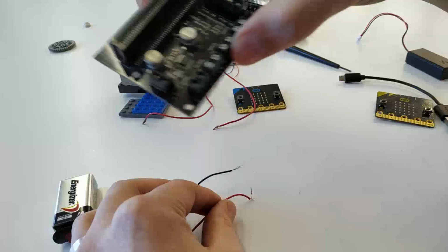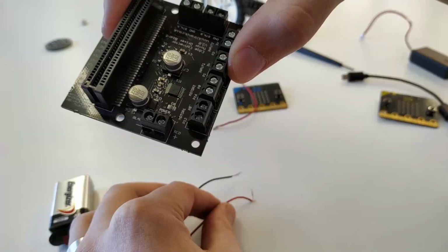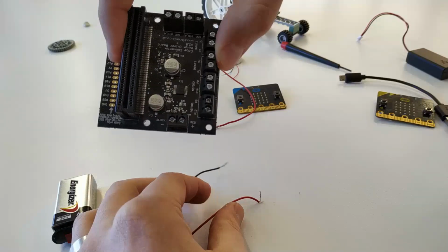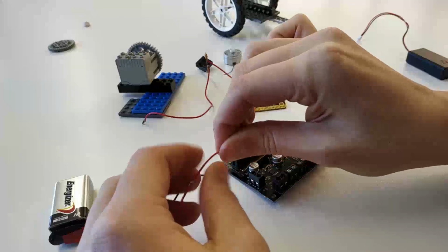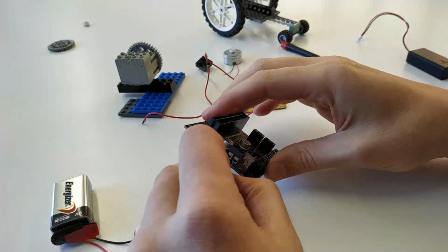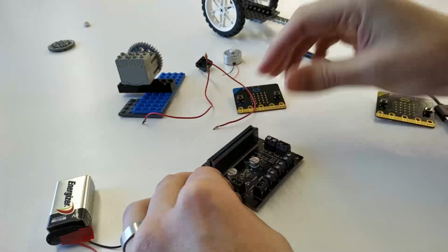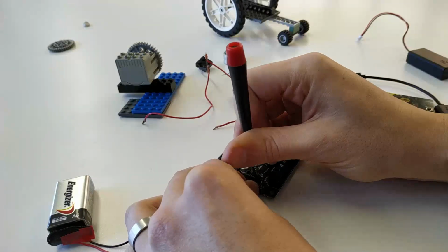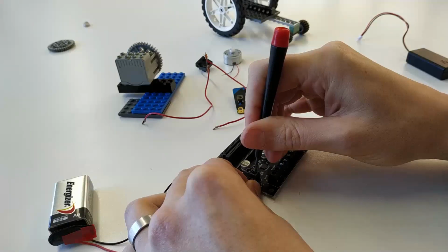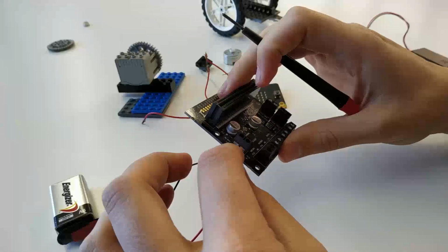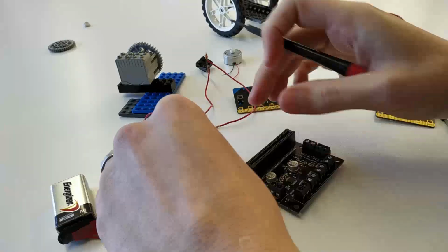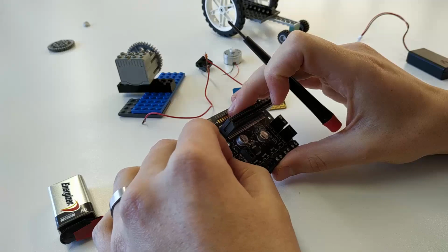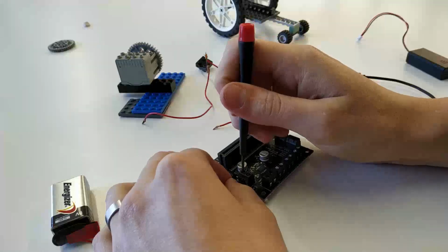Now, very nicely, our motor driver board has actually labeled for us red and ground, which you can sort of see there, red and black. Black is generally the color that is used for ground. So for these, what you'll do is carefully insert it there, use your screwdriver to clamp down. My wiring isn't great over here just because I've done this many, many times with this wire. I really should just strip it and get a bit more, but this will just be for illustrative purposes. The black one, the ground, goes in here as well.